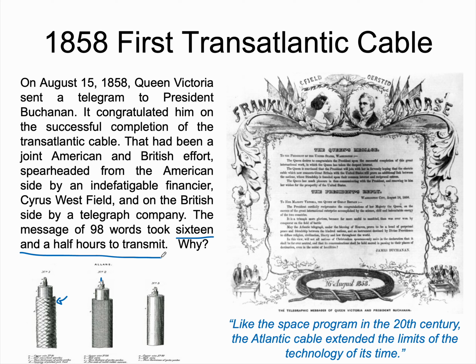In the end, they kept raising the voltage to the point where it became dangerous to be a telegraph operator on this line. But with a larger voltage, a larger potential, it would charge more rapidly. And by putting a larger load on it, it would discharge more rapidly. In the end, they pushed it so hard they eventually reached what's called a dielectric breakdown, and it actually shorted out under the Atlantic, which was the end of the cable.